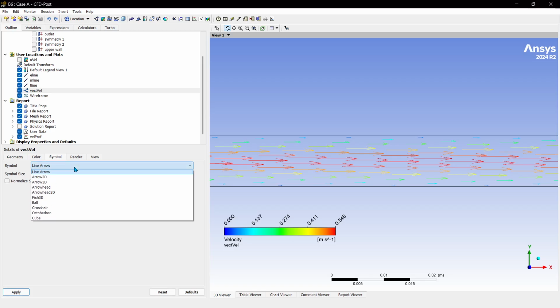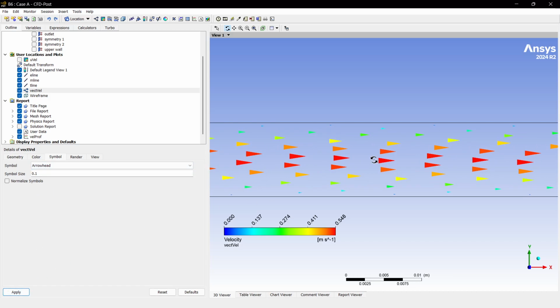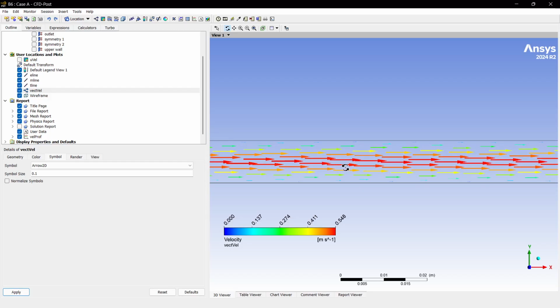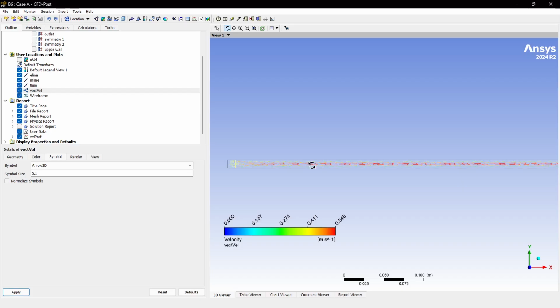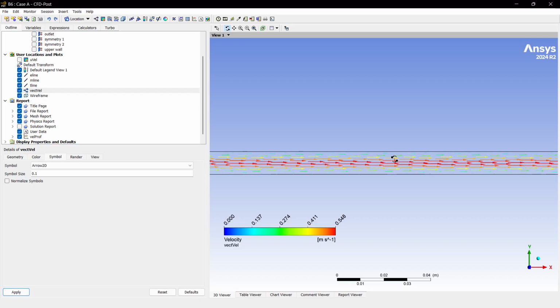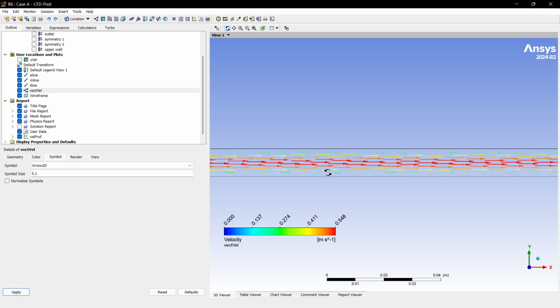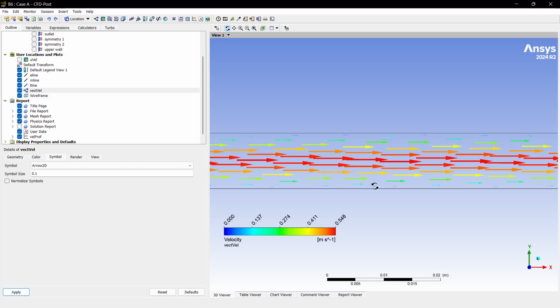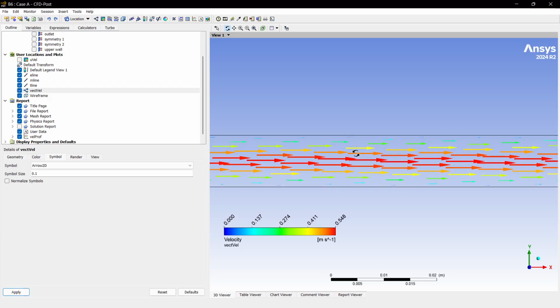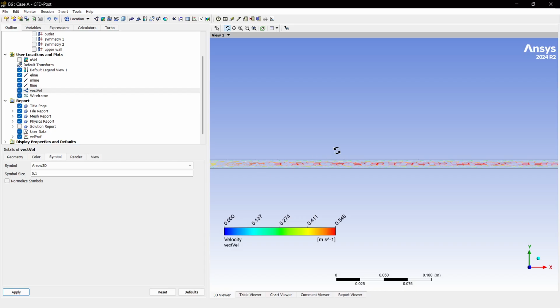And instead of line arrow, we could do something else. I don't think I'm a fan of these ones. Oh, there you go. That's much nicer. So yeah, you can see the velocity vectors are just basically going along the path, and the velocities closer to the wall are pretty slow. That's a boundary layer forming. So yeah, that's done with. We're done with the Poiseuille flow.